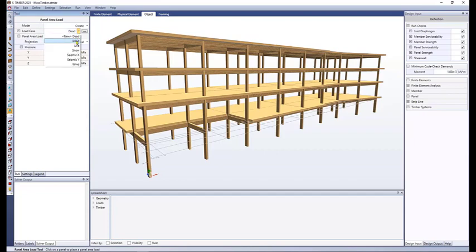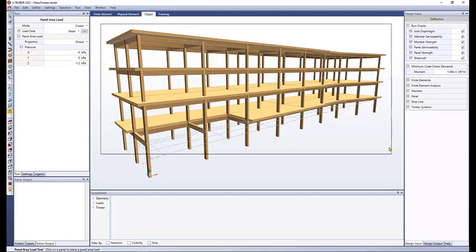You can select the load case of interest, in this case dead load. You can define the projection, so I will select global, and define minus 1.2 kPa for all my stories in this structure. So this will be assigned to every panel I have. So I just need to, with the mouse, click and drag all those panels to assign the load.